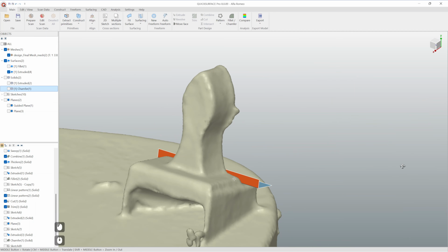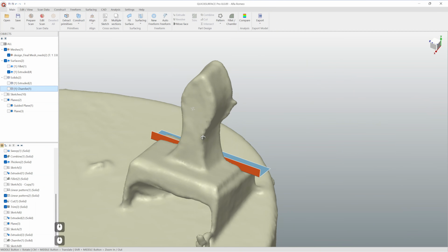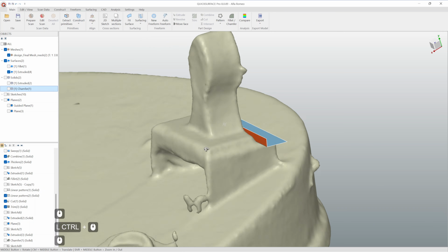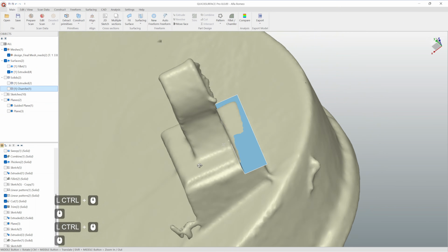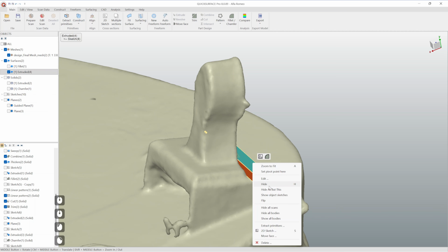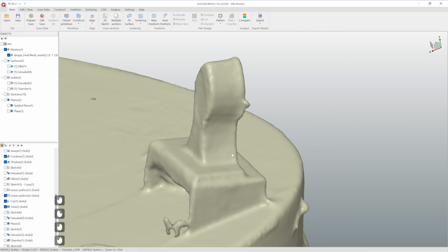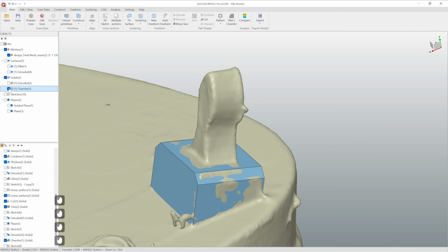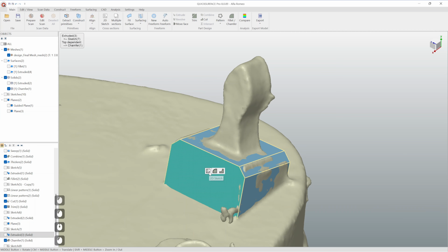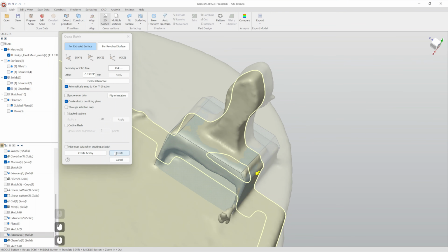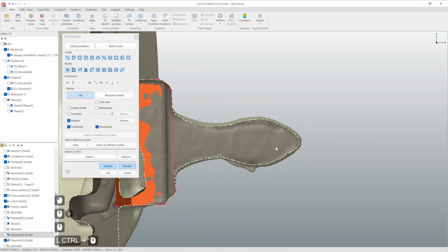But before trimming something out, I can see this tab probably is a single feature here. So basically it's not a different part fitted onto this plastic, but it's also injection molding and was made all together. And in order to recreate that one, let's see, I will use this plane to create another cross-section sketch. Let's go somewhere in the middle of it. Hit create.